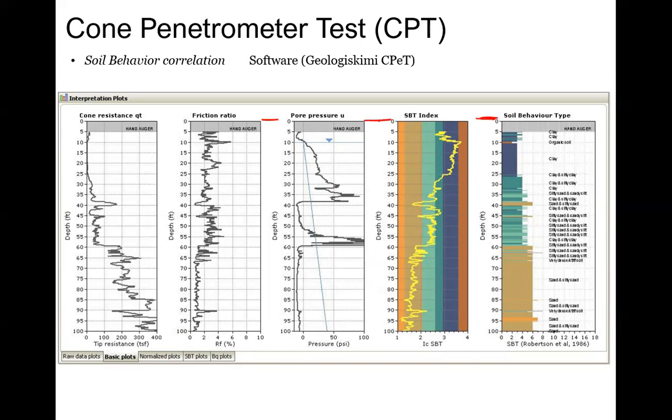So what we're looking at here is the ground surface elevation. So the ground is up here, and then we have depth shown here. And you can see they even color code it, which is always pretty. And we can see what type of soil we're most likely penetrating through with depth, as well as the cone tip resistance and the friction ratio too. So although CPTs don't allow us to collect soil samples, they still give a lot of information and at a much higher resolution with depth compared to the SPT.